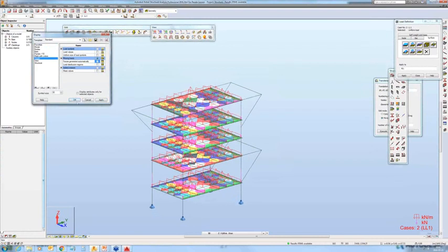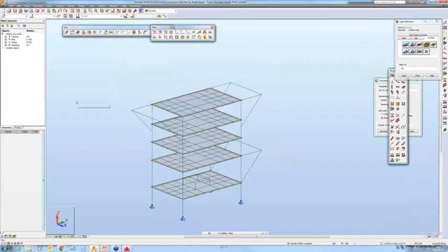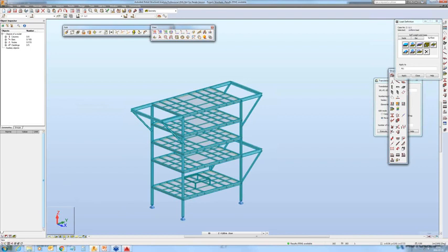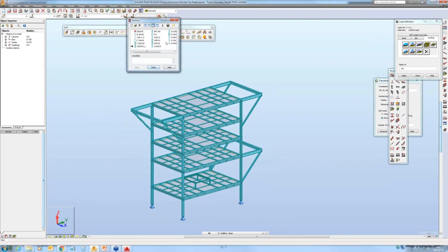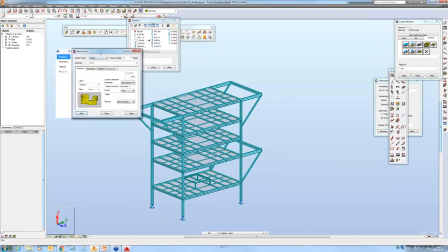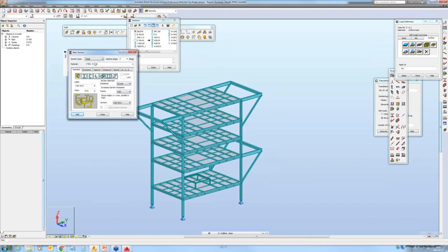Of course, now we can go to the steel design module that I mentioned and change the size of the beams or columns so that they match the loads. Let's skip that. Instead, I will simply manually change one of the sections of the beam. I'll go to steel and I will select American W sections, and for example, I will use some large sections so that it is visible.